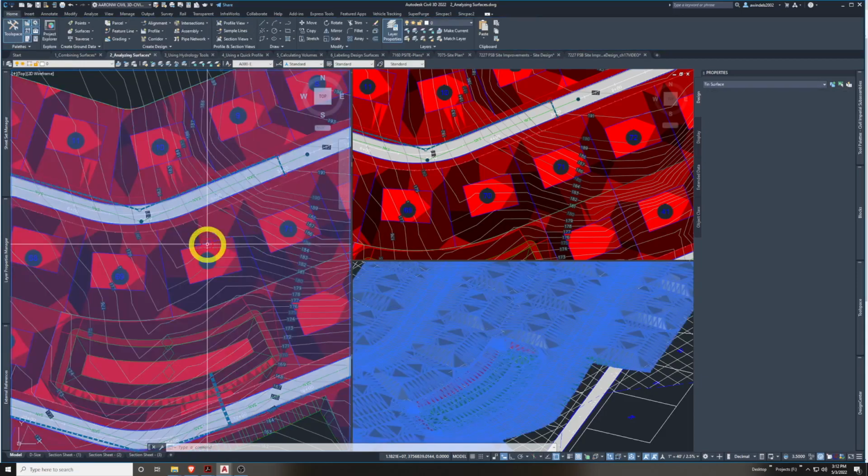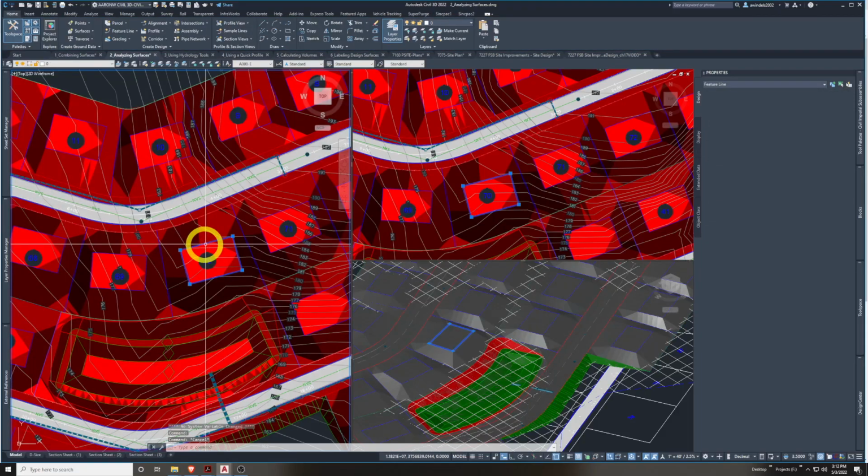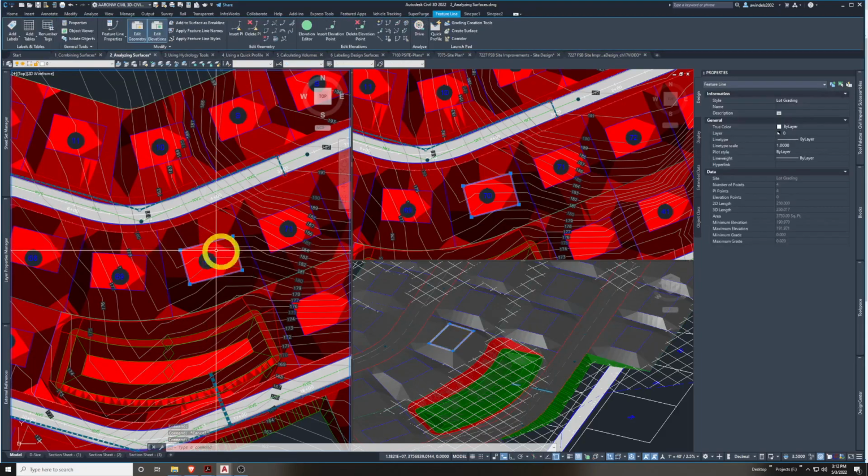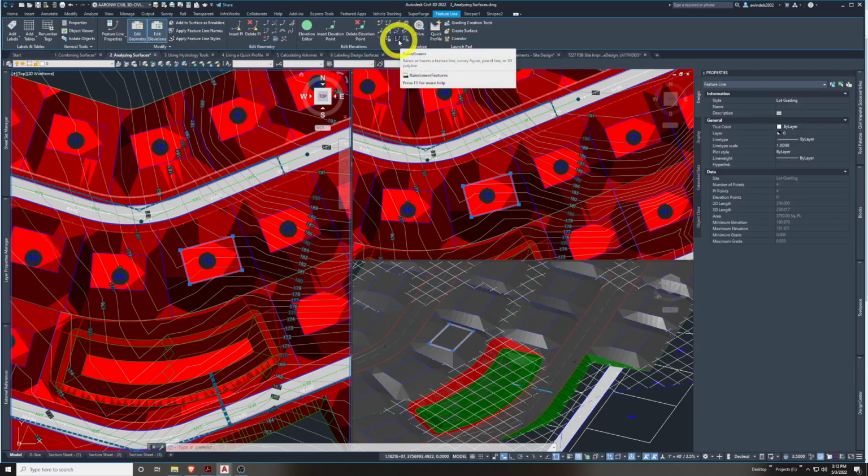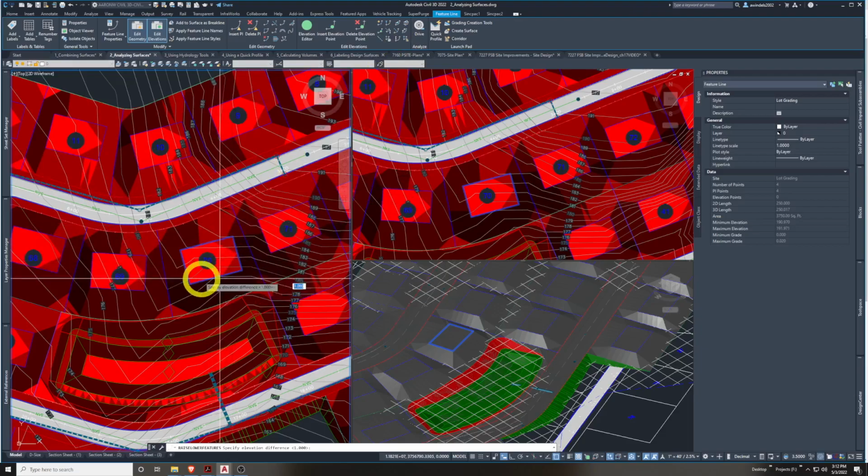We're going to pick the blue rectangular feature line. There we go. And now we get our contextual ribbon for feature lines we learned so much about in chapter 17. We're going to edit it, and we're going to do the raise lower command. We're a little high up here, so we have this thick, high slope here. We want to lower this pad. In my dynamic prompt, I have this on, but it also shows in my command bar, as always.